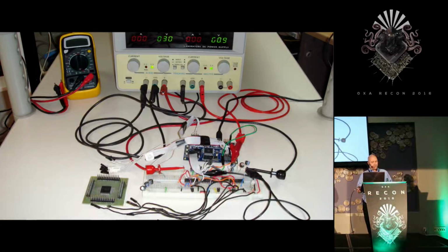The other parts on the breadboard are an oscillator to provide some of the clock inputs that are necessary for the ACP to run. There's an inverter and NAND gate that I use to cut the clock out during the glitch time. To simplify the test setup as much as possible, I removed the ACP from the set-top box and soldered it to a breakout board. In this process, the battery-backed RAM is disconnected, so all the keys are lost, but for the purpose of developing a glitch, this was okay.